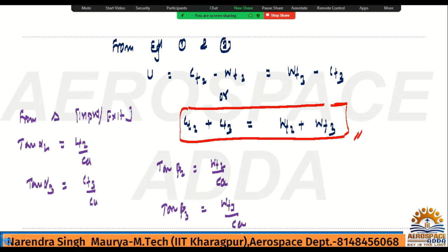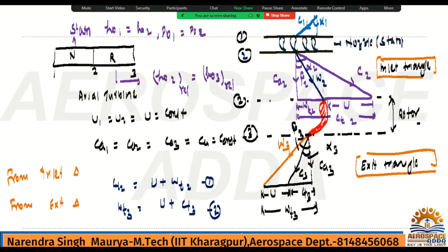So that statement I had given, if you remember, that air angle, which is alpha 1, alpha 2, alpha 3, is the angle of the absolute velocity from the axial. So in this velocity triangle I have taken alpha 2, beta 2, measured from the axial component, and similarly alpha 3 and beta 3 I have measured from the axial. This is the axial velocity, and from here we have measured. So remember, alpha 1, alpha 2, alpha 3 are the air angle, and it is measured from the axial component or axial velocity. Similarly beta 1, beta 2 and beta 3 are the blade angle, and it is measured between the relative velocity and axial components. And alpha 2, alpha 3 are the angle between the absolute velocity and axial velocity component, from the axial direction.